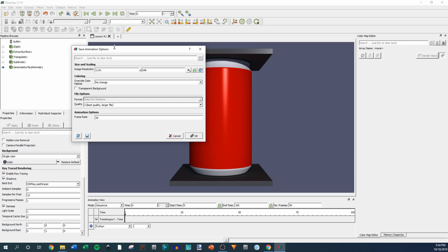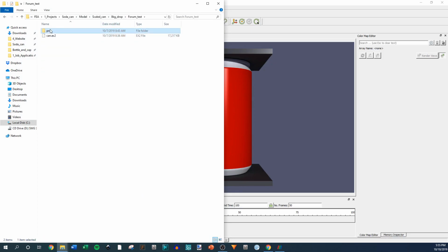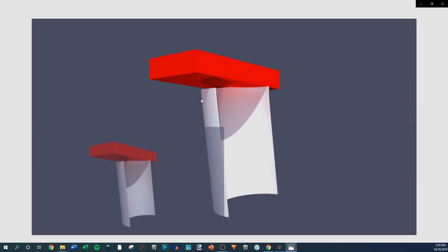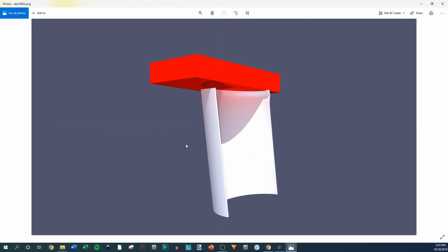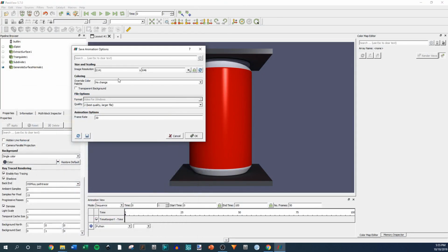If you change its resolution with this window being this small in this version of Paraview, it's going to do weird things. It's going to do something like this. We have this weird quadrant picture in the picture. It's bizarre. And then from there on, there's this faint cross hatching. You can probably barely see it, and it's really obnoxious. It took me the longest time to figure out why it was happening. So I was stuck in this resolution.